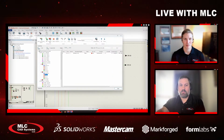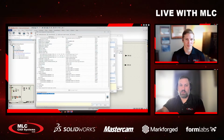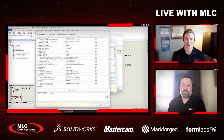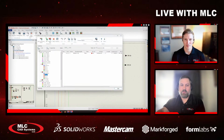And so if I go to the properties of this, it says L1 in text and then a number. So this is based on the variables that you're using to define this wire number. So you could have page number as part of it, or color, or gauge, whatever you want. Cool. And so these have L1, L2, L3 because they're part of what we call a multi-style group, but it's just phase one, phase two, and phase three.